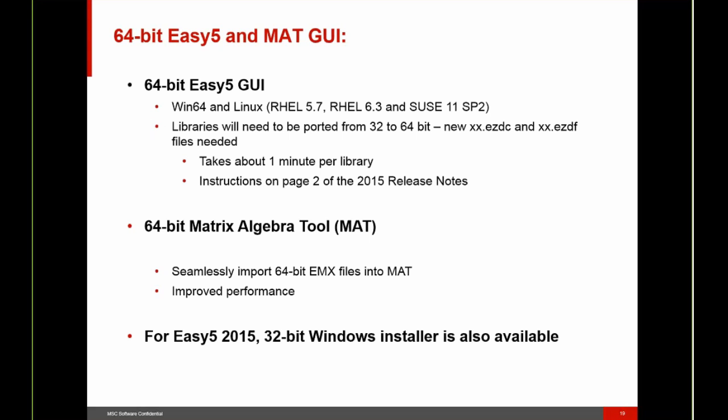To take advantage of this, for those of you who have your own in-house libraries that you've developed and are using, you will need to port those libraries from 32 to 64-bit. Just pretty much in the same way that you would need to do if you were porting from, say, Windows to one of the Linux platforms. It's the same sort of process. It takes about 1 minute per library. The instructions for doing that are on page 2 of the 2015 release notes.